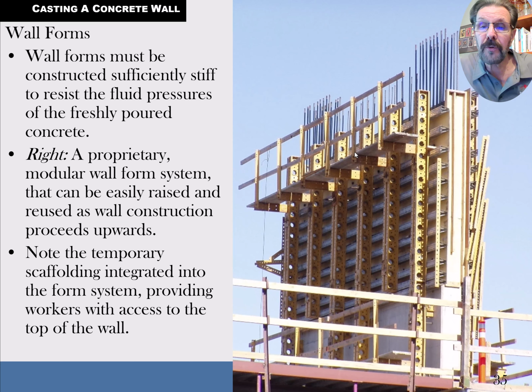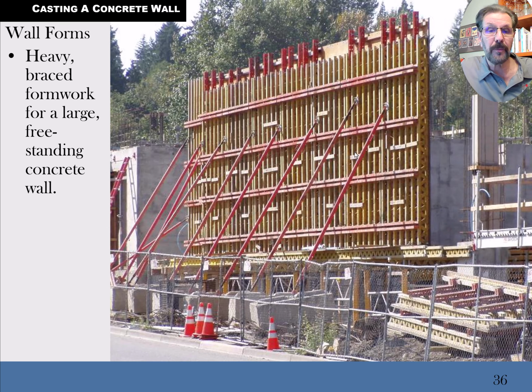Here's some steel forms. They're so heavy that they have scaffolding built into them. So that's a good system to have for scaffolding. But it's a heavy enough thing you would never physically pick these things up. These would be picked up with a crane instead and put into place. Even if you're picking them up to do some slip forming, you do that with a crane or a jack of some kind. Here's some more forms used here. They look like they're steel forms. They might have plywood on the actual surface that the concrete's poured against.